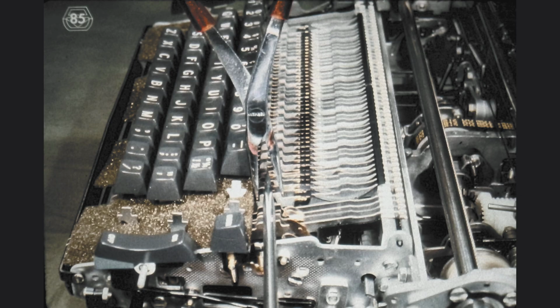This screwdriver will prevent inadvertent excess forming action on the horseshoe, which could very easily happen without the screwdriver limiting the amount of bending. Using the screwdriver will enable you to control the amount of forming you do on the keylever. Do not attempt to close the horseshoe without using some tool to limit the amount of bending. When we close the horseshoe adjustment, we decrease the clearance between the keylever pawls and the interposer lug.